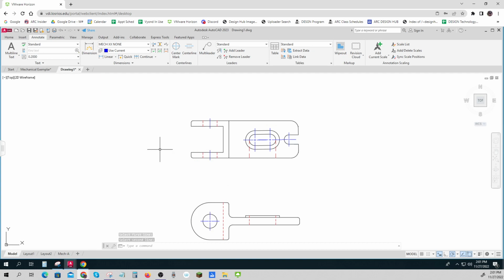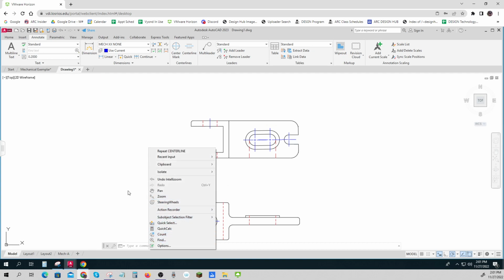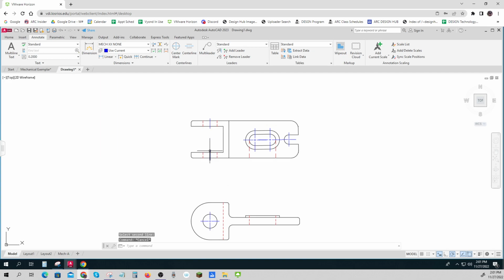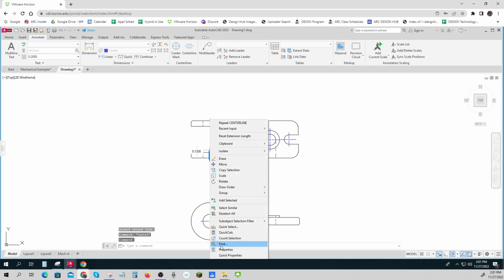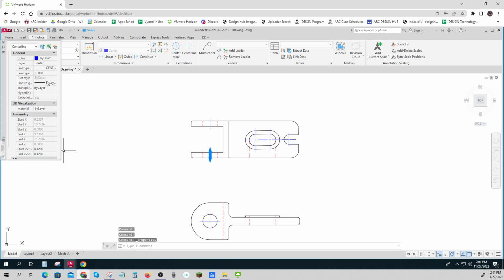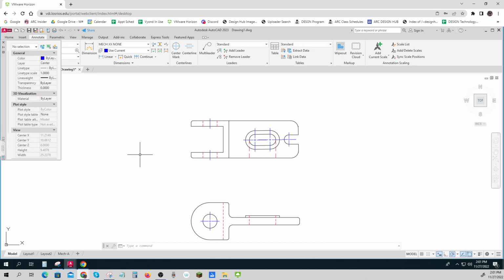This actually meets standards, but if you'd like to, you can change that. It's not required because the standard doesn't say to, but it's called your line type scale. You can change that to say 0.75, maybe even 0.5 to get that to show.